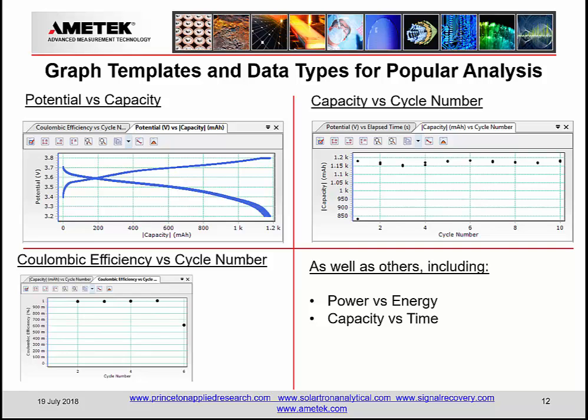You can see the Coulombic efficiency starts off very high, meaning I'm getting almost all the charge out that I put into the battery, and then around cycle 6 in this particular test, there was a dramatic decrease in the Coulombic efficiency, meaning that I put in a lot more charge than I got out. That tells you that the battery has faded or may have caused some sort of issue that we can go in and study further with other advanced techniques.